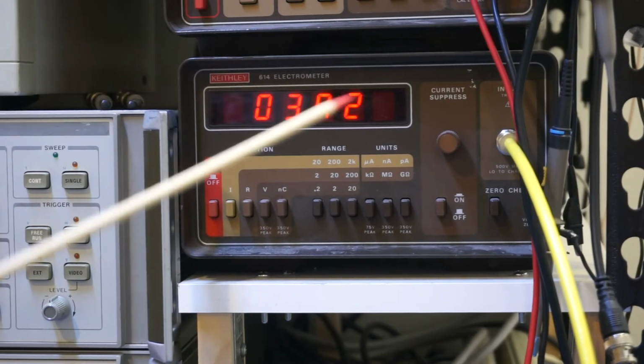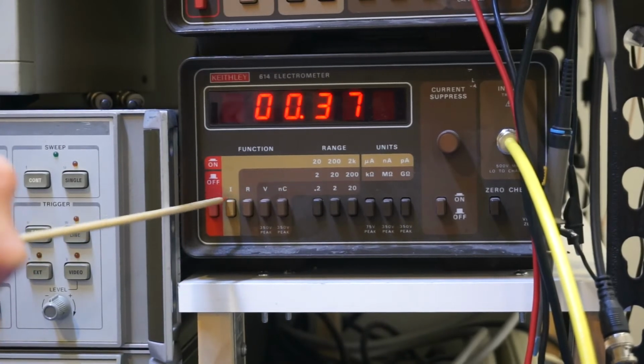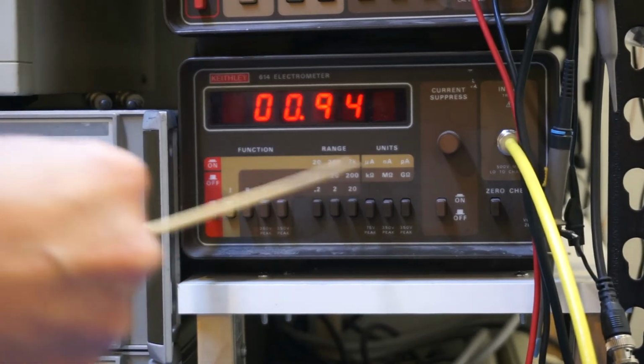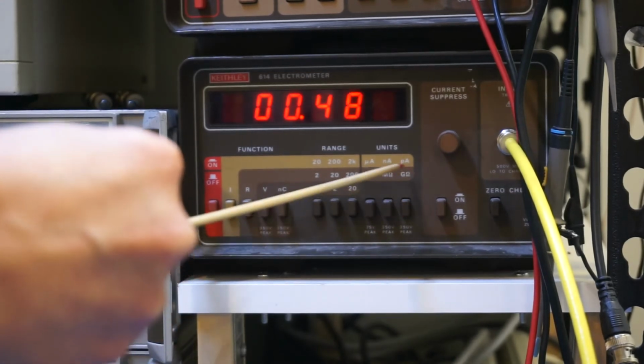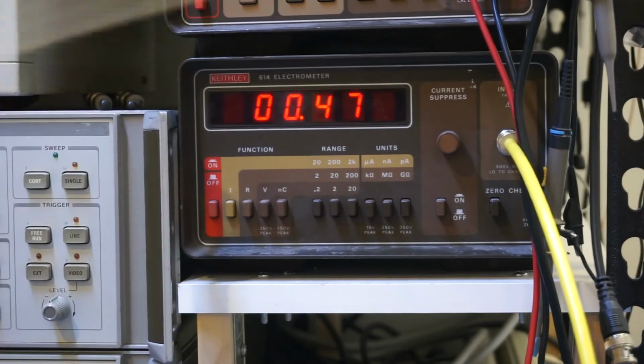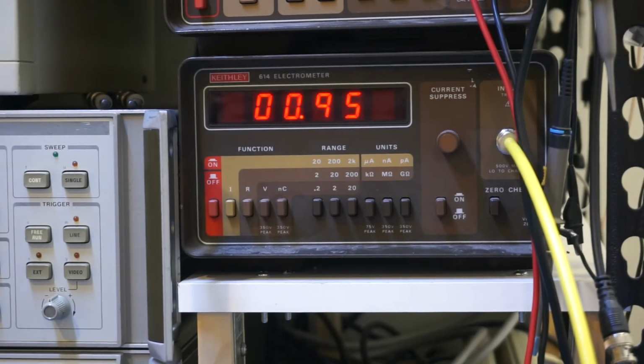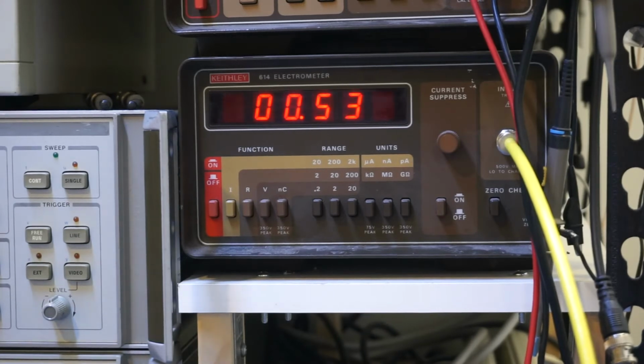As you can see here, I set the electrometer into its most sensitive current range mode, and right now we're in the current range, so we read the uppermost line, and it is set to reading picoamp, and the range is 20. So right now we're reading from 0 to 20 picoamp. And as you can see, even with the shielding we put in, because the other side of the cable from the voltage standard is not shielded, even if I'm just waving my arm here, you can still see that the current jumps quite a bit. So we just have to wait till it settles for each of the readings.